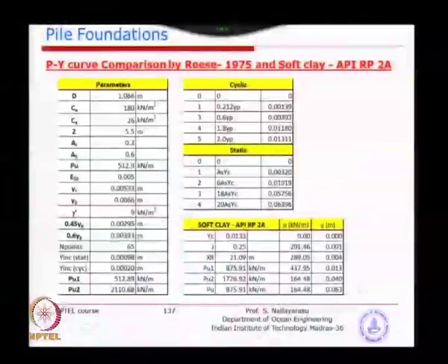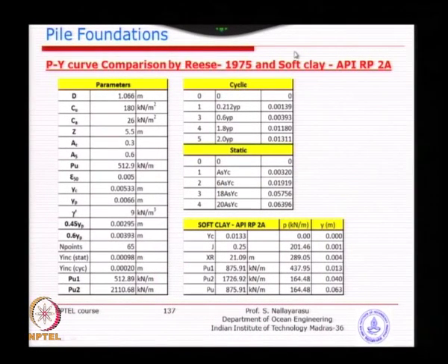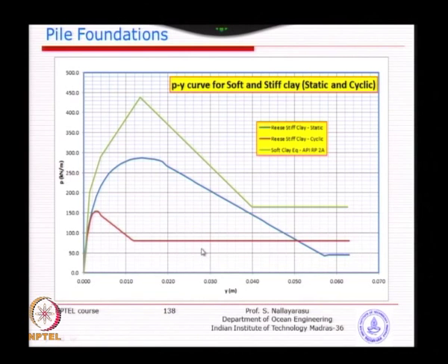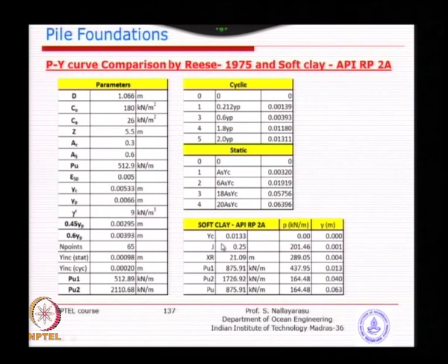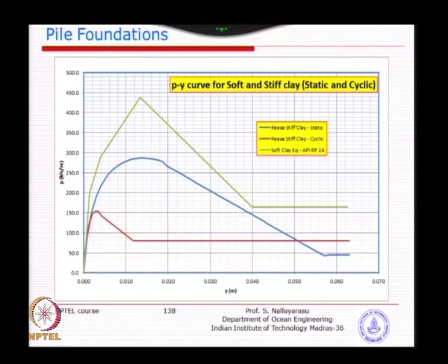I tried to plot, you could see, for a particular diameter, the soil resistance. I just wanted to show you, in a spreadsheet you can put every one of them, all the equations we learned about: soft clay, hard clay, soft clay at near surface and hard clay at near surface. You can just see the comparison so that you will understand what significance it makes.